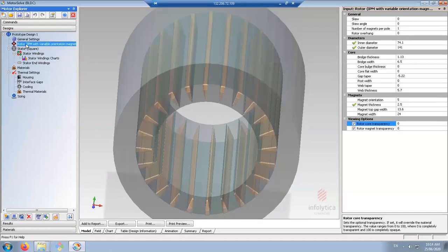So as I said, you can apply the skewing to the rotor and the stator as well. If you have an induction motor, instead of a permanent magnet rotor, you will have a squirrel cage or round rotor, right? In that case, you can again apply skewing to the slots of the rotor, not just the slots of the stator. Okay.